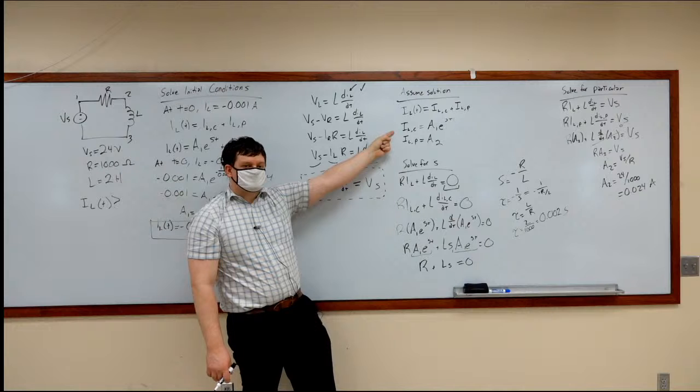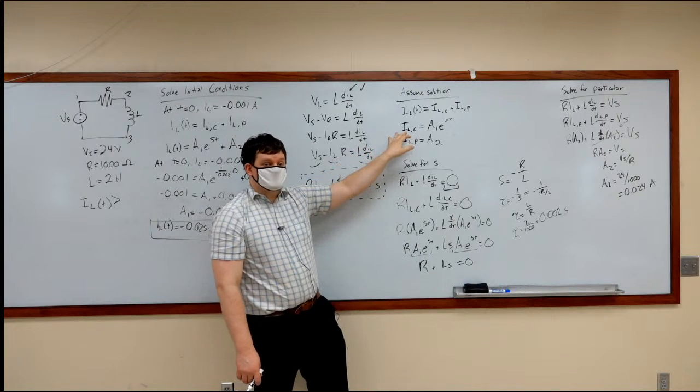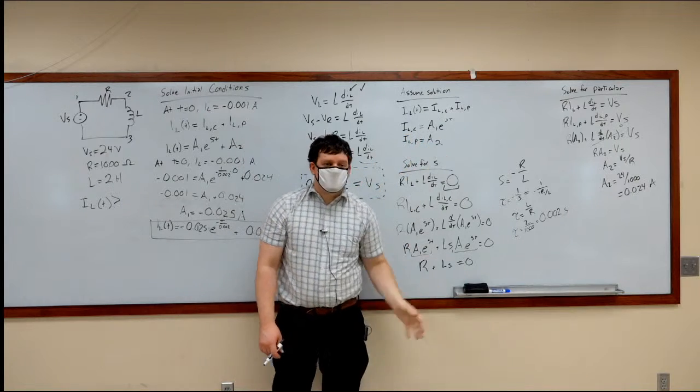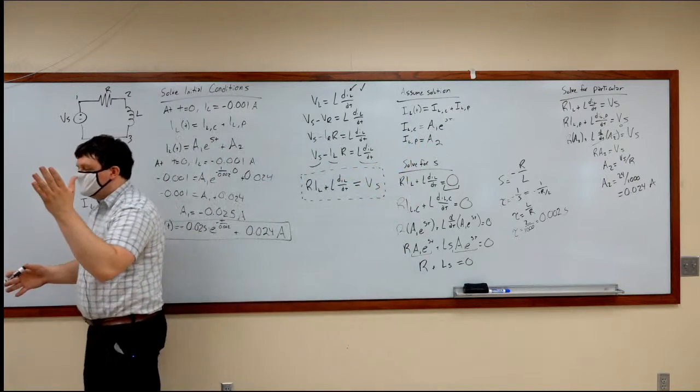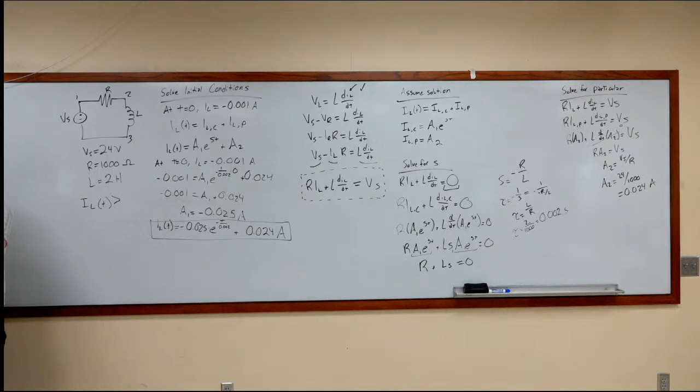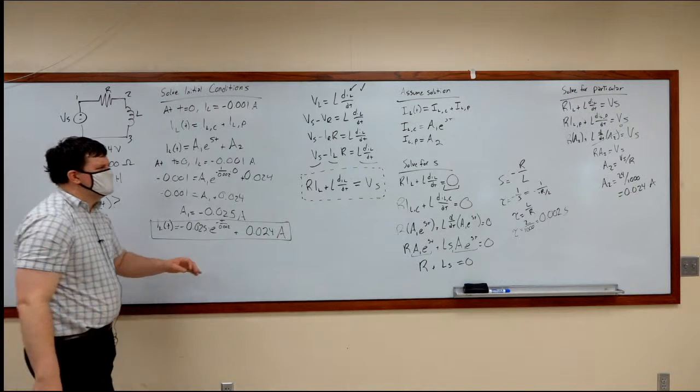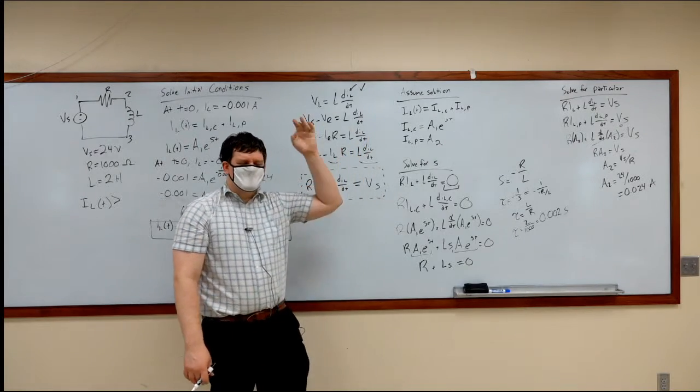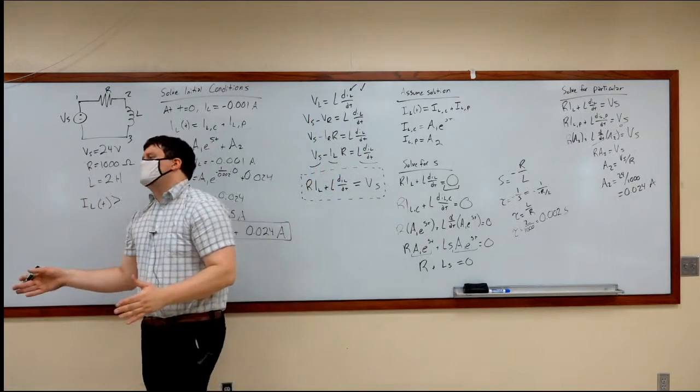Part of the parameter changes with time. It's the transient portion, right? It's the one that is time dependent. What a transient is, it's the difference. It is the way that the system behaves when conditions change. At t equals 0 seconds, there is a negative current flowing through this, and all of a sudden maybe our voltage source changes, and now it changes to something else. All this is doing is this says, how does the system change from where it's at to where it's going to be?